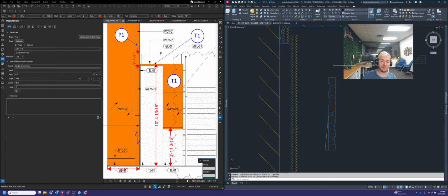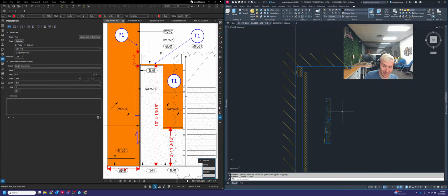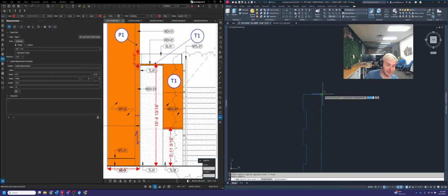The only real difference between these two cleat systems, profiles are exactly the same. The difference really is the core material. When you have wall panel cleats, they don't need to be as durable. They'll make those out of MDF. If you have ceiling panel cleats, of course, they will need to be more durable because you don't want a panel falling down from the ceiling and hitting somebody on the head. That's made out of plywood, which is a lot more durable here for this application. It's able to hold a little bit more weight as well. So that's only on ceiling panel cleats. Wall panel cleats, again, particle board, and that's all they need to be.